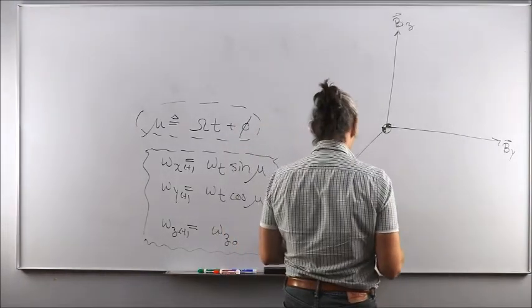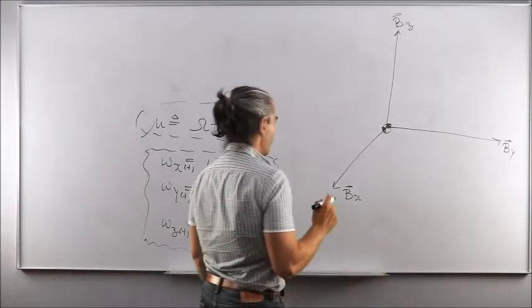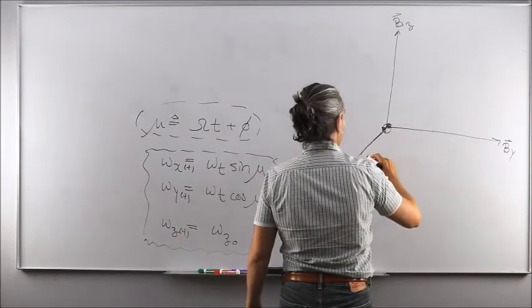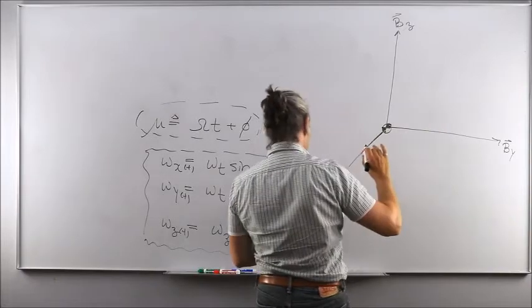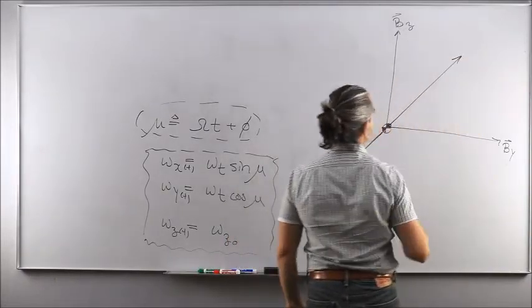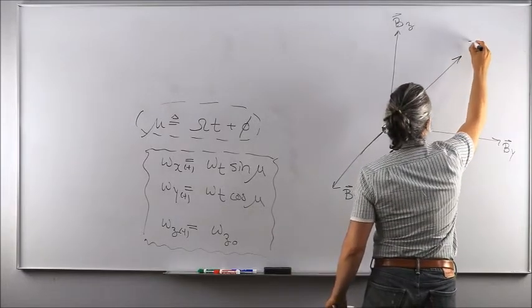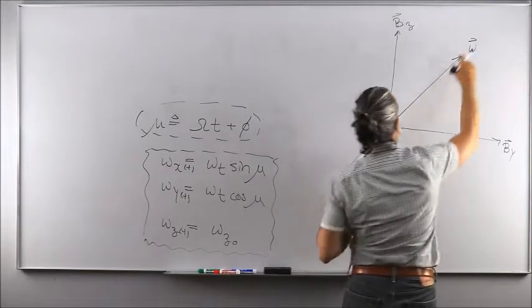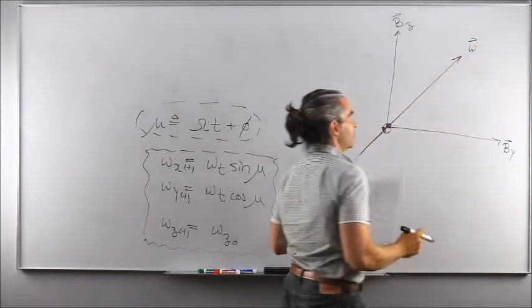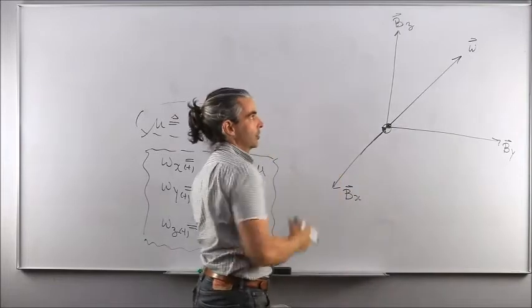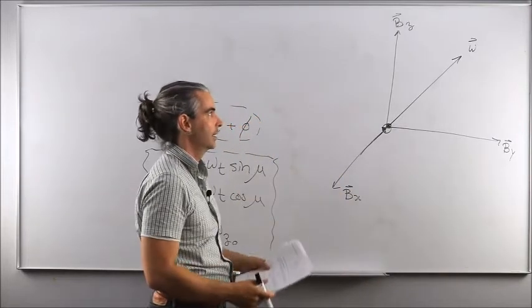So what do we know? Well, we know that the norm of my angular velocity vector shall remain constant at any time. So this is the angular velocity vector. It means that this vector will not shrink or expand as a function of time, and the reason for that is because there is no torque applied to the rigid body. Torque-free attitude motion.